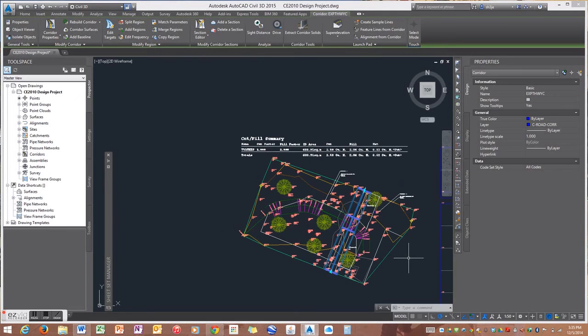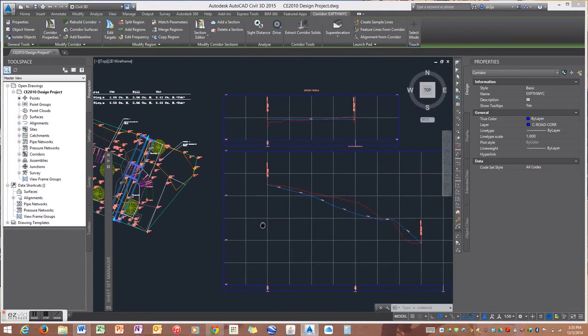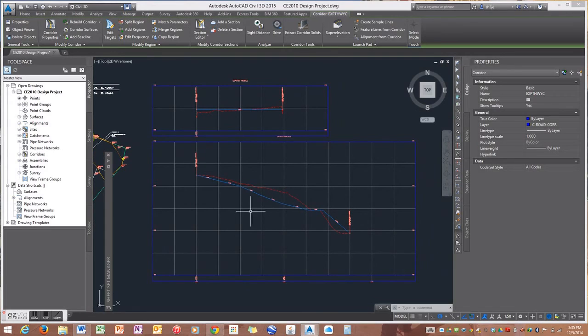Again, to highlight the cut fill, you can see here from my proposed profile pathway, most of this cut here at the top ends up going to fill in at the bottom, and also partially goes towards the bioswale infill, although most of that is specialty soils and rock.